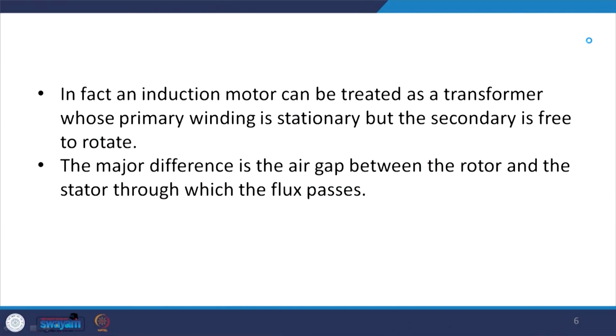In fact, an induction motor can be treated as a transformer whose primary winding is stationary, but the secondary is free to rotate. This way we can carry out the treatment of it. And the major difference is the air gap between the rotor and the stator through which the flux passes.